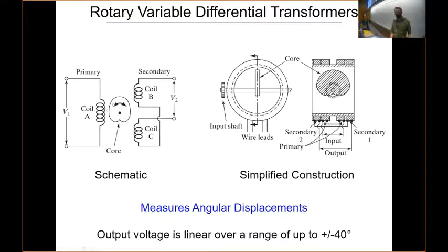In this case, it's closer to coil B, so it's sending the magnetic field up here. If it rotated out of the page and down, in this view, it would shift the magnetic field to coil C. Here, more of that signal is being induced into coil B and less in coil C. And from here on out, it's the same thing: in series, out of phase.